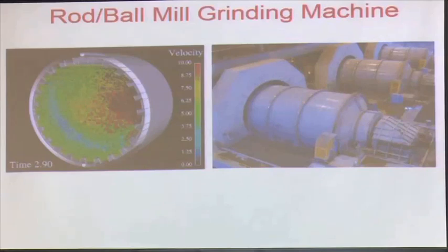That water also helps because when you are rotating it, there will be a lot of heat produced. Because of the heat, what will happen? Apart from energy losses, there will be more wear, because at a high temperature the wear is more, wear of these surfaces, wear of my balls, wear of my machine components. It also reduces the noise, because it will be very noisy, and environment-wise that is not correct. That is why the water plays a huge role.